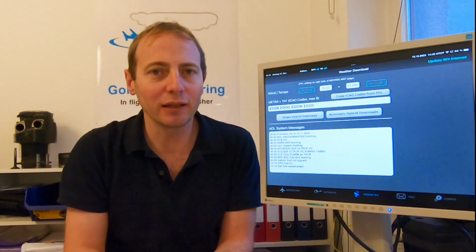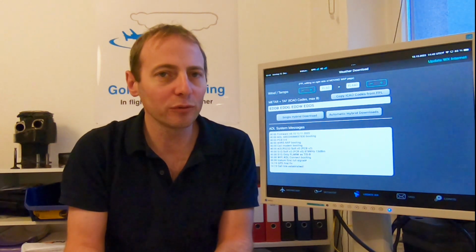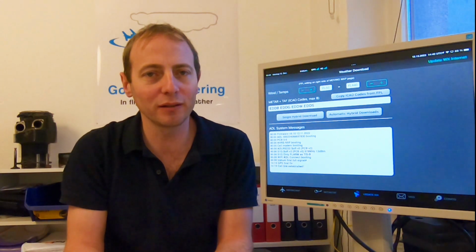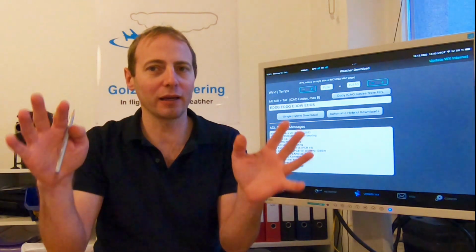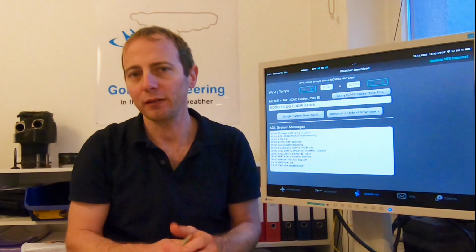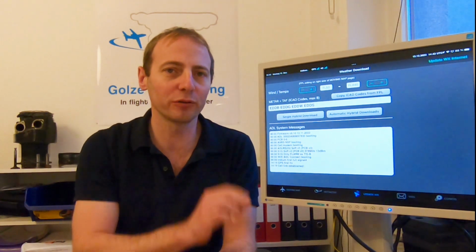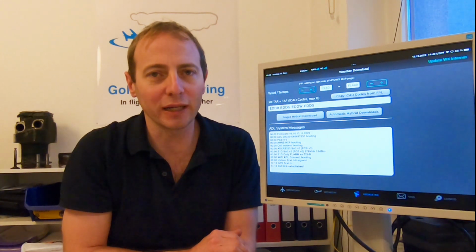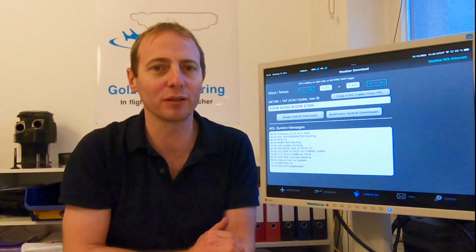If you have another ADL device, it will be a satellite download, or you can use the app to download the weather data. The important thing to remember is that the ADL device cannot transmit the weather data if you do a weather download for the entire European or US or whatever region. You have to do a weather download just for the corridor, which in flight is the only option anyway, but if you're on the ground you might get confused, so this is something to remember.